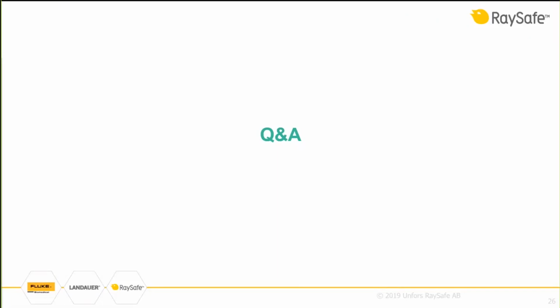Next question, in the presence of neutrons, will the silicon detectors have signal inducement? We have tested the 452 and it is not sensitive to neutrons. So not a neutron detector, and it's also not affected by them. Okay. Next question, is there a specific type of calibration request needed when using this meter to capture scatter from industrial cabinet type of X-ray scanners?